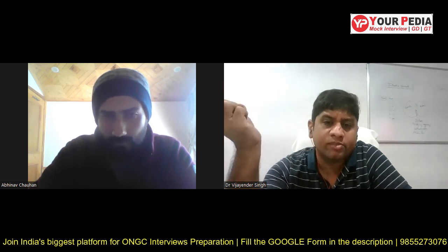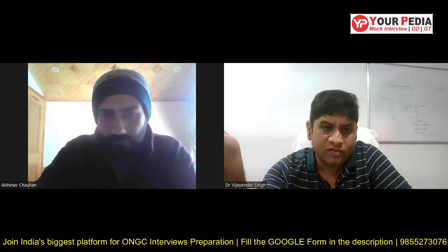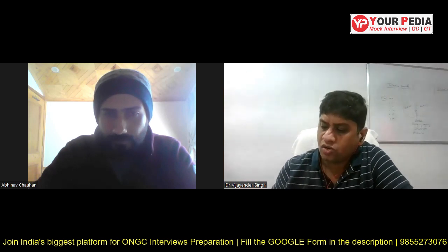Newton's second law is the starting point of the forces on these turbine blades. M dot into dV, that is in the fluid, because in fluid you don't have the concept of mass. This is the concept of mass flow rate. Mass flow rate is the density into Q, discharge, rho Q into V. That is how it comes. And when the plate is moving, then relative velocity comes into the picture. And from there you get the formulas, then Pelton, Francis, and all these come.